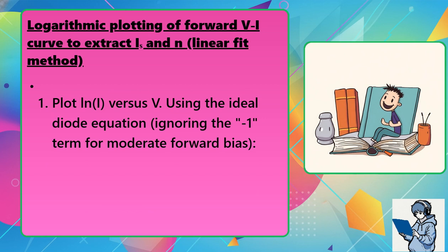I is approximately I_S times e raised to the power of qV divided by nkT. Taking natural log gives ln I equals ln I_S plus q divided by nkT times V.